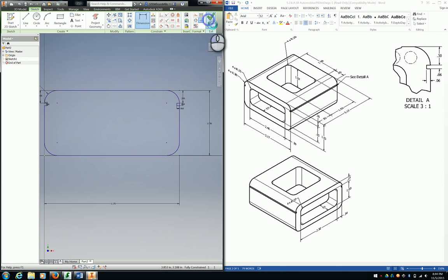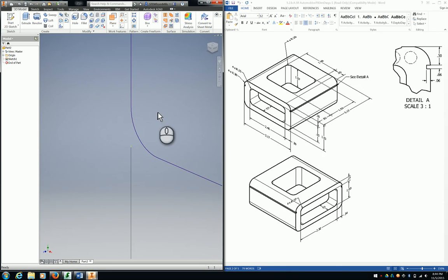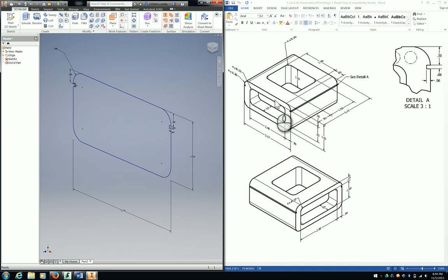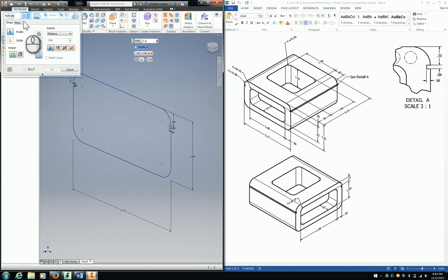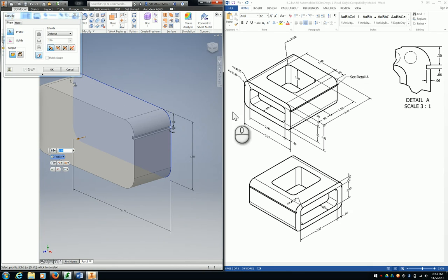It's going to be finished. We're going to extrude it. We'll worry about cutting the stuff out later. If we do this all in one, that would be a problem. Let me just tell you why before I extrude this. When you do an extrusion, you can only extrude one profile, one direction. You cannot extrude it back or extrude it out and then extrude these different lengths. It doesn't work like that.